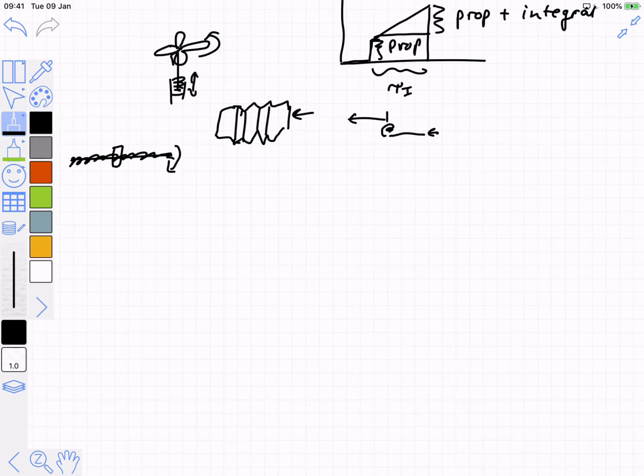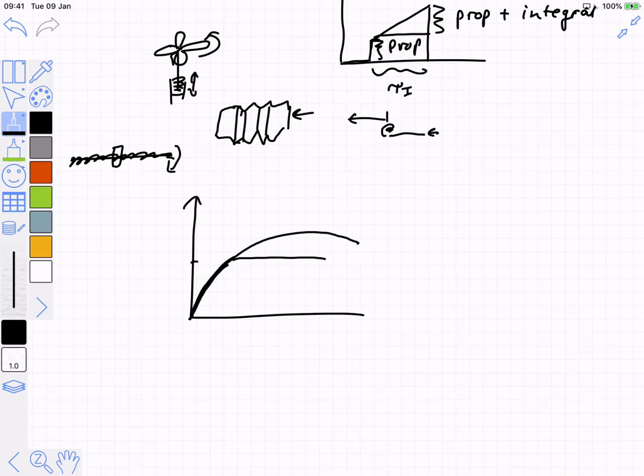And so in terms of your action, what you're seeing is this is kind of what you asked for, and this is actually what you get, right? So you're at the limit, and the controller still keeps integrating because the error still isn't zero. Still turning, still increasing the error integral.